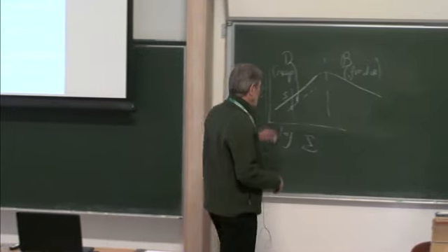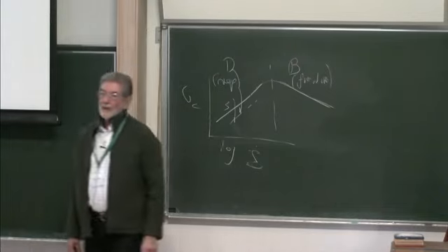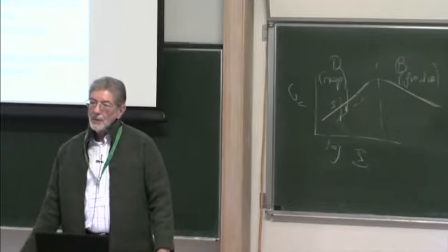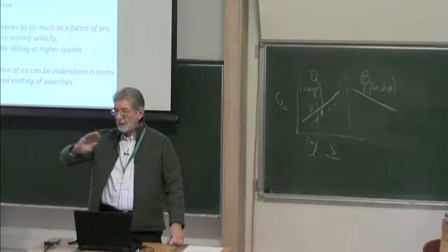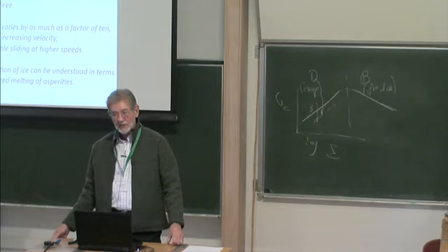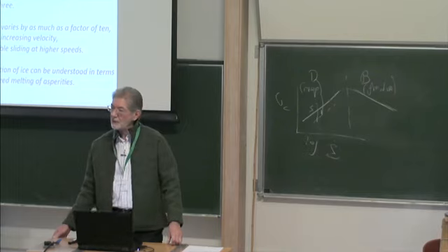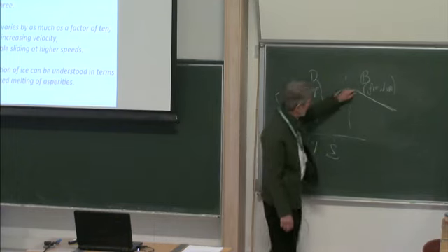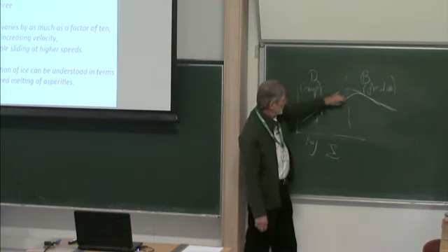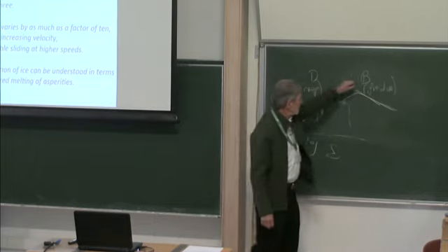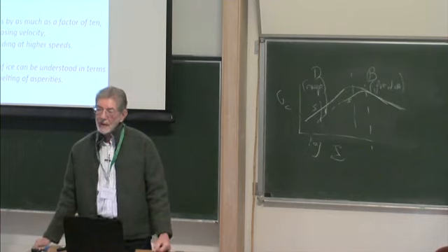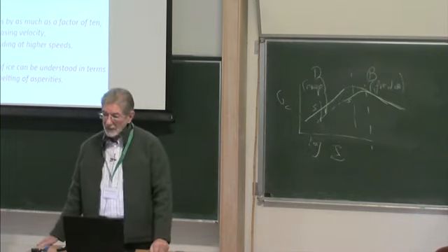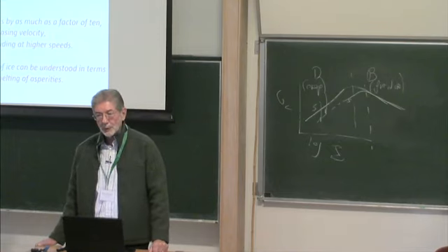In the brittle regime, at least in the measurements we have done in the laboratory, on complete failure envelopes both triaxial and biaxially loaded ice, we cannot statistically, at least at the conditions investigated, -10, -5, whatever, distinguish brittle compressive strength of sea ice from freshwater ice. So what it means is then that one comes up here, and so we have freshwater and saltwater ice. The difference is that the transition from ductile to brittle behavior is at a higher rate for the sea ice, and yes, we've measured that, and it is at a higher rate by about an order of magnitude.